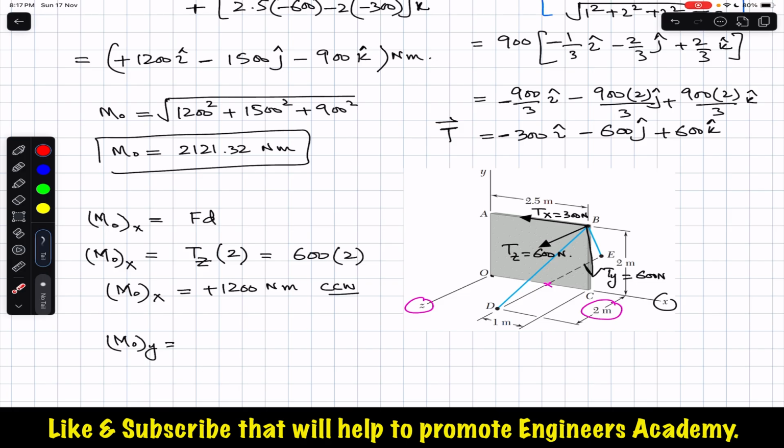Similarly, now the moment at O in the y direction, or about the y-axis, is equal to, again we have to look at these three components and think about which component is producing the moment about the y-axis. Now, as we can see, Tx is intersecting with the y-axis. So the perpendicular distance, or the moment arm of Tx from the y-axis, is 0. So Tx is not going to produce the moment about the y-axis.